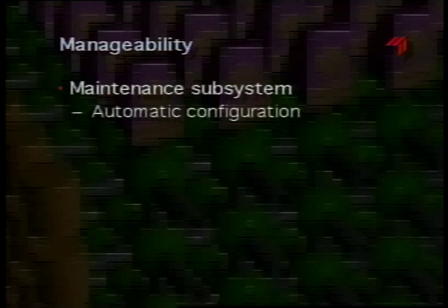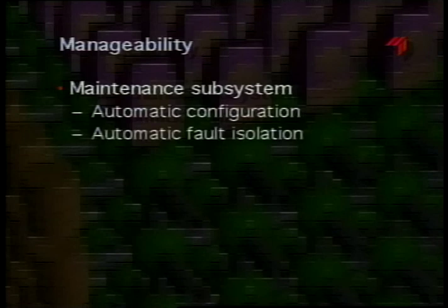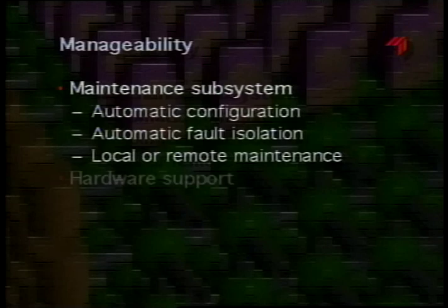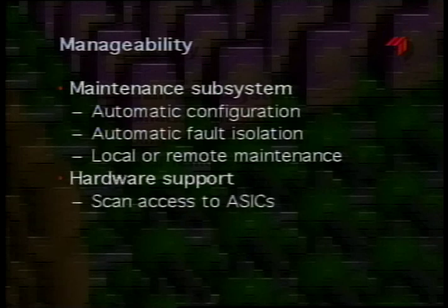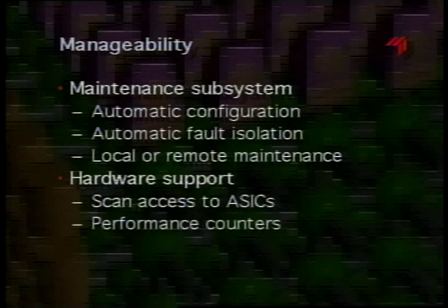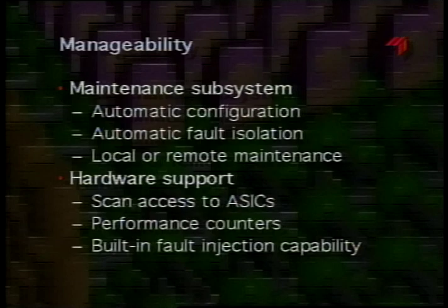Another key problem to solve in any kind of network design is to make the network manageable. In ServerNet, we've designed a separate maintenance subsystem which takes care of automatic configuration of the network, automatic fault isolation, and allows either remote or local maintenance of the system. The same maintenance system includes scan access to all of the ASICs so that we will be able to determine their state and have access to non-volatile memories on each of the components to be able to determine the configuration. The maintenance system also has access to performance counters to determine how the network is operating, and it also controls the fault injection capability that we were just talking about.